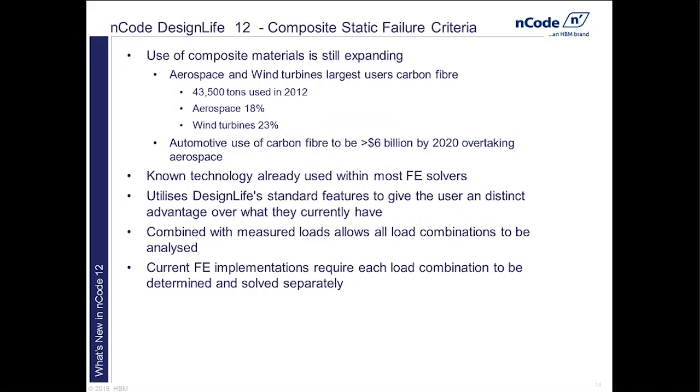This tool is actually just using known technology, so most of the standard FE solvers will have the same static failure criteria built in. But within DesignLife, it allows you to look at the static failure criteria over the complete load history applied to the component. So you can apply your real measured loads and look at your static failure criteria for all those different load combinations.